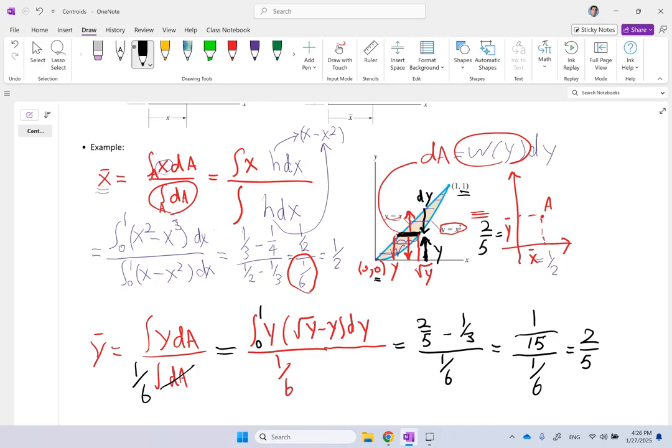So that is where you should put it, at x of 1/2 and y of 0.4 or 2 over 5. That is where you can squeeze that entire surface into a single point, and you can show it with this symbol. This symbol here is what? The symbol of centroid. If you draw it bigger, it's like this, and then these two sides are basically painted. Whenever you see this symbol, that's the symbol of centroid. So that's where it goes. Good, done. So this is how we can do it.